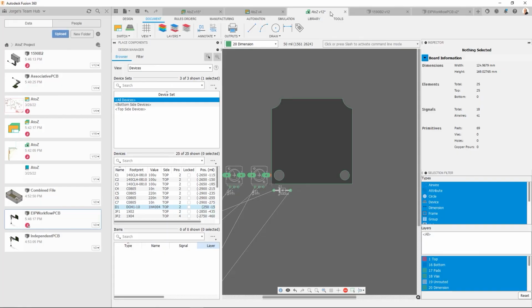So these are the four options that we wanted to go over for creating your PCB outline. The first one, which is the simplest, is just drawing it on the 2D PCB itself. Options 2 through 4 all derive their outline from an enclosure. So you could argue that the next easiest is option 2, which is creating an independent PCB. Snapshot in time, has no link back to the original sketch. But if you do want to be able to track changes and update the PCB outline as you make changes in the enclosure, then options 3 and 4 are your best bet.